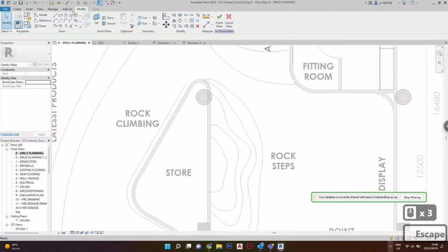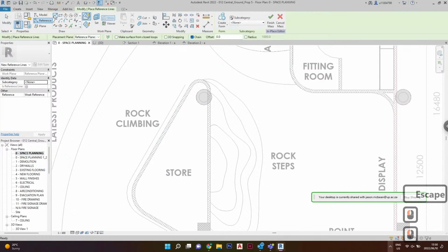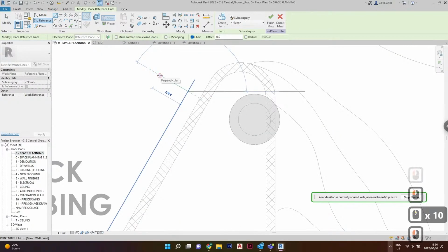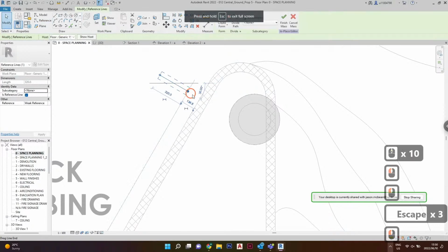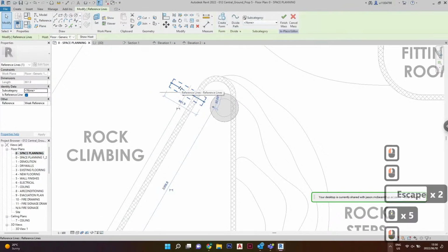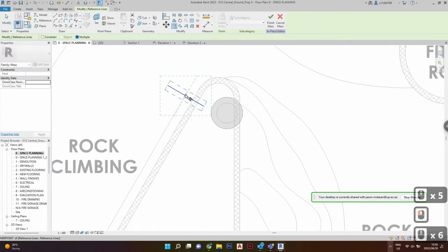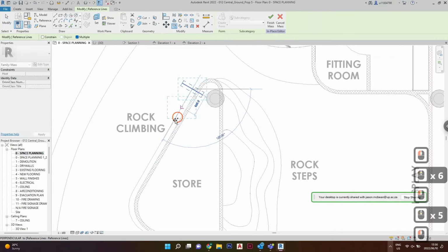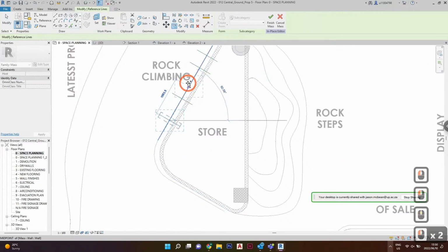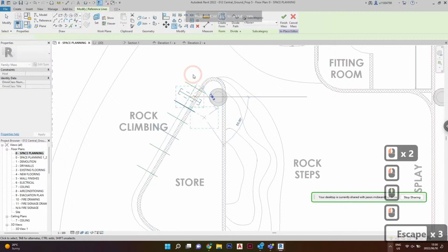So maybe let's do that, but this time I'm going to use a reference line parallel to that, because technically this acts like a grid now, but this is not that important for the levels. This is a secondary type of grid. Now I'm going to use the copy tool again. Copy, so that's where it will start. Here you just add a couple of these in the grid that you want, and you do this roughly because you're going to use your dimensions again to help you. Okay, so now that's it there.